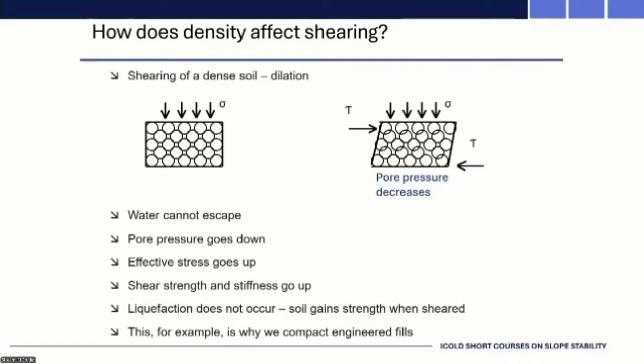Cannot do that. So the pore pressure takes that additional compression. That tendency for a volume decrease is accounted for by an increase in the pore pressure. Sorry, I think I might have got ahead of myself there. I'm talking about a dense soil here, sorry. Just scrub what I've said the last minute.